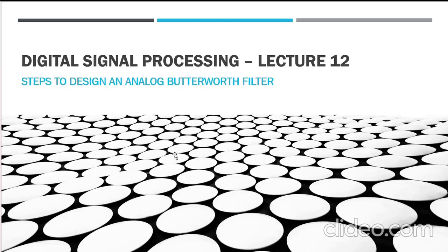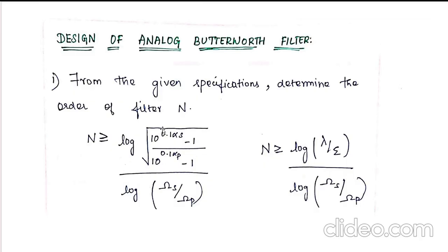So in this video, we'll discuss the steps involved in designing an analog Butterworth filter. Totally there are 5 steps involved. We'll see one by one. The first step is, from the given question, we will have to determine the order of the filter, that is n. This is calculated by using two formulas, under two criteria.